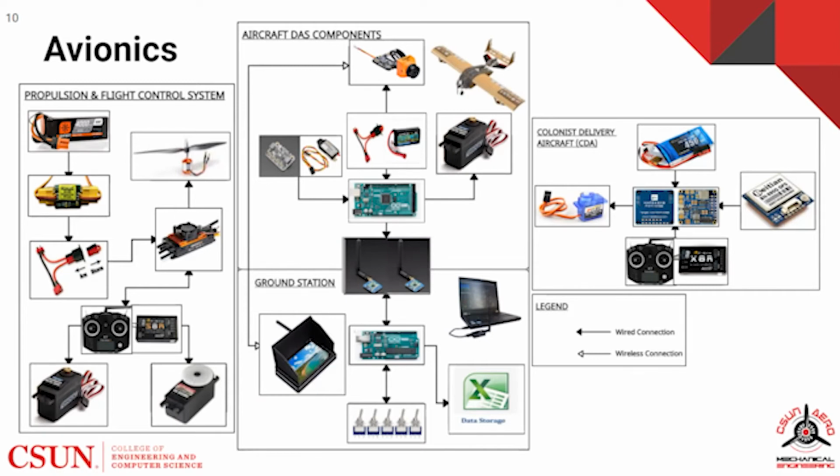A new addition to our flight control system is a 3-axis gyro stabilization unit, which was integrated into our radio receiver controls. This was useful in preparing our aircraft for varying weather conditions and providing fast control response to different air loads. Once our selections were finalized, all results were experimentally verified during ground testing with the servos and a custom designed 3D printed thrust stand for propulsion.